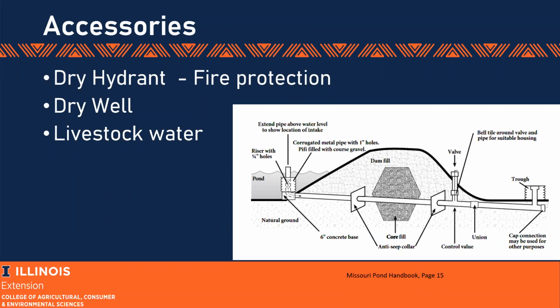Being able to pull water, because they're often way away from any other facilities and in need of large amounts of water. The trick with that is essentially you build that in, it can be built through the dam, or it can be put into the edge of it. And a dry hydrant means that it's got a pickup point that is protected and below the water surface out there, comes out to the edge of it, and a riser comes up, with a specific connection on it. The fire department can come up, open the cap on it, connect to it, draw water through it with their pump equipment, vacuum, and use that to pump either into the truck and fill the truck, or they put a pump truck up there and they can pump straight to the fire from it.